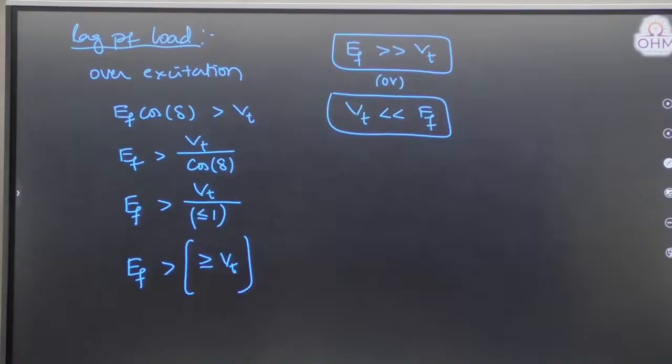Kalidas, actually the rotor part of a synchronous machine is not laminated here. It is excited with DC, and also in order to create damping torque, the circulating currents in the rotor will also create damping torque. Generally, we don't laminate the rotor core. Unless it is a special machine, the rotor core is generally not laminated. As I said, unless it is used for some special applications.